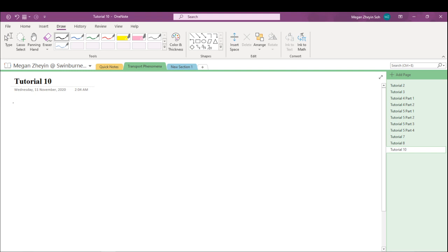The rate of mass in is given by the velocity multiplied by the area and the concentration, U0 A C at z, minus U0 A C at z plus delta z, minus the rate of gas consumed, which is Kc (1 minus epsilon) rho P A delta z,